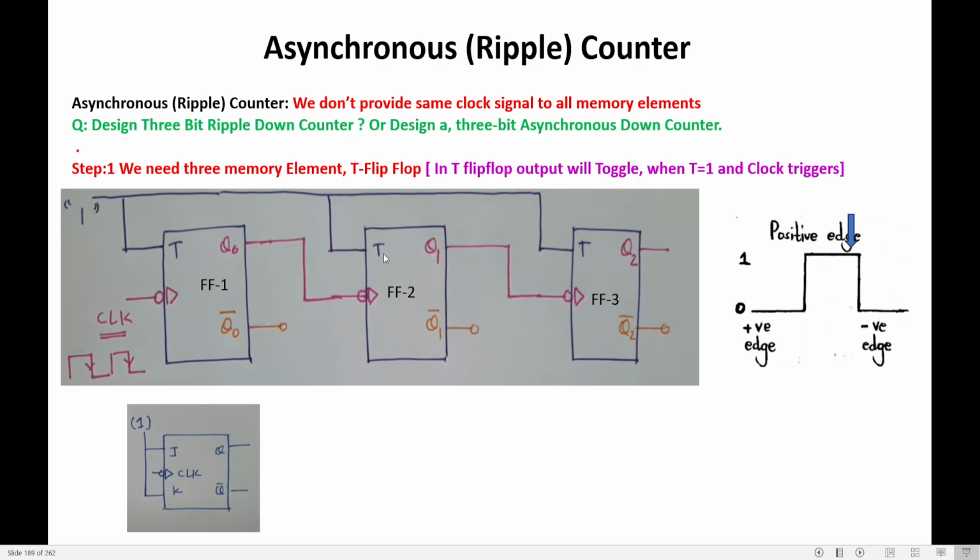Now we are going to see the down counter, and we should understand this counter will work only on the negative edge of the clock pulse. Can you see? If this is a clock pulse, this is the positive edge and this one is the negative edge. When it moves from 1 to 0, I call it the negative edge. This arrow mark indicates the clock will work on the negative edge. The bubble is negative. The triangle is edge. Negative edge. Clear? So let us start working.